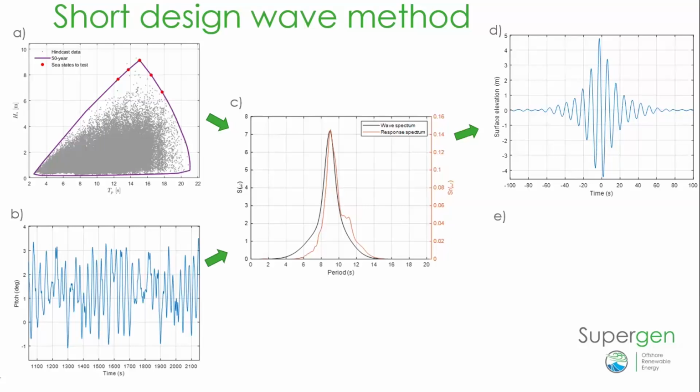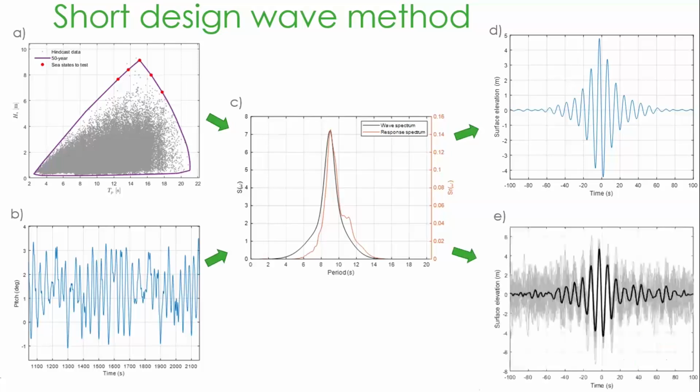Using the RAO data, we can come up with this single focus wave shown here in the top right figure. So it's slightly different to the largest wave. And then we can also constrain this into multiple random backgrounds. On this bottom right figure, we can see these grayed outlines in the background, the different realizations of this top wave constrained into different backgrounds. And you have the average given by the solid black line.